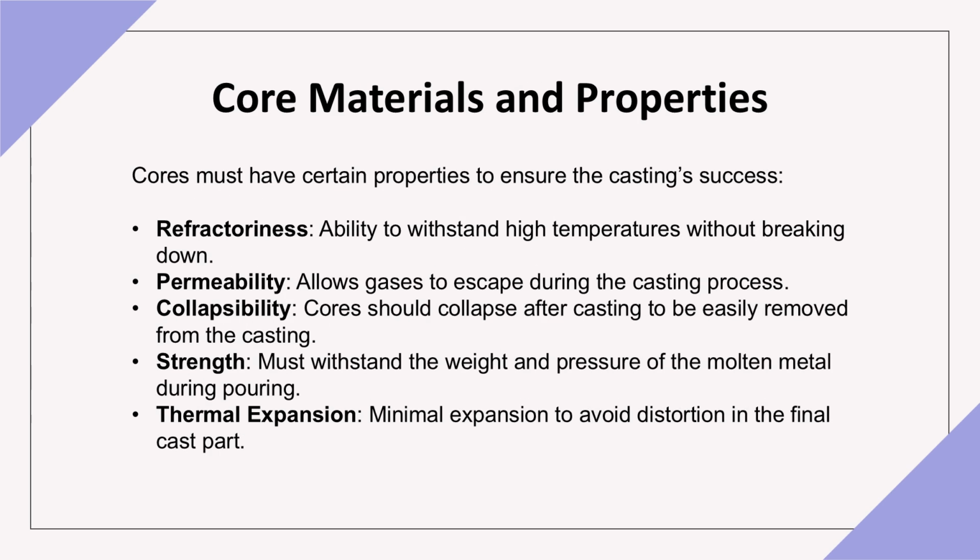Cores must possess specific properties to ensure the casting process is successful. Refractoriness, the ability to withstand high temperatures without breaking down. Permeability, allows gases to escape during the casting process, preventing gas-related defects.